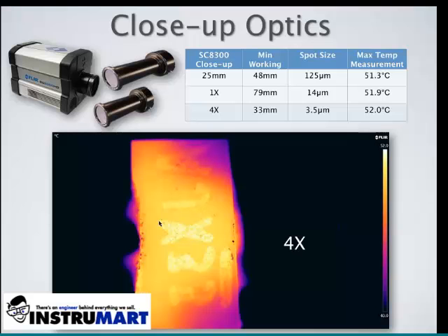And this image that is displayed here is our IC, or integrated circuit. This is the target of interest that we wanted to measure earlier, that is roughly 3 millimeters by 2 millimeters. And you can see that not only do I see the target and see the temperatures, I start to see the temperature profile, and I can even now see the lettering that is inscribed on the top of this IC. So if your application calls for even better magnification than 50 micron, you can resolve all the way down to 3.5 micron in the infrared spectrum with a FLIR camera.